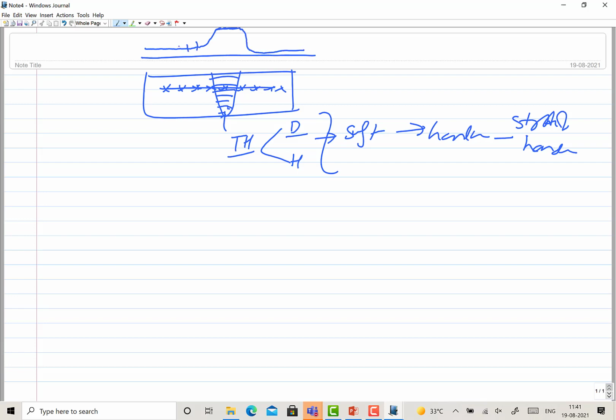So this suggests the base metal hardness, and whenever there is a gradual change, rise and then down, this increase in strength and hardness is contributed by the transformation of soft phases to hard phases, and that has led to the increased strength and hardness.